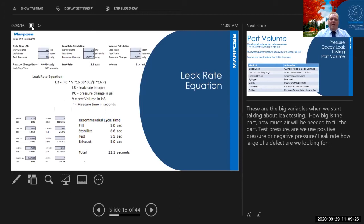I don't want to spend a lot of time on this. If there's something you'd like to see or get a copy of, feel free to contact me. This is what I use for calculating cycle time and things like that, and it's all built upon what we refer to as the leak rate equation. It's just the leak rate in cc's per minute, and it takes into consideration the pressure change and how long we're going to measure for.